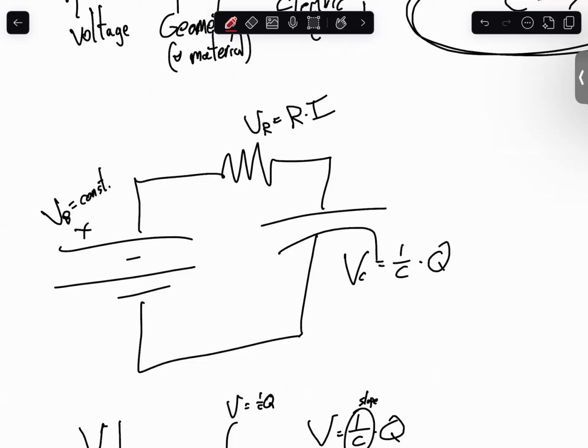There's less and less. What can you say about I now? I is lower. Does I turn around? Does I ever go negative? No. The closer and closer this voltage gets to 9 volts, the slower and slower the current will put more charge on here. Again, this is complicated. Think this through. The closer this voltage gets to 9, that tapers off to 0. But this voltage never flips around and becomes negative. We never have current flowing in the opposite direction.